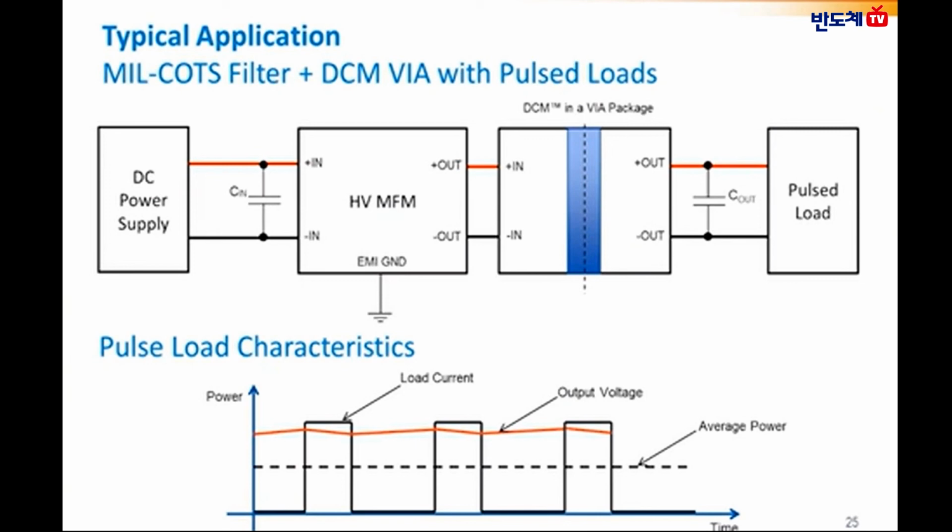One of them is adding ground planes. Adding ground planes on outer layers will potentially suppress the high frequency noise coming out of the signal traces, which are buried in the inner layers. And adding a ground fill.